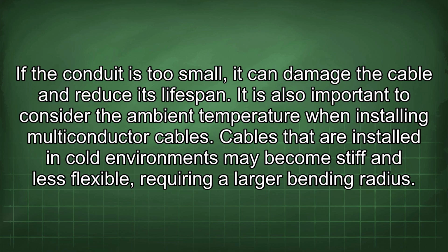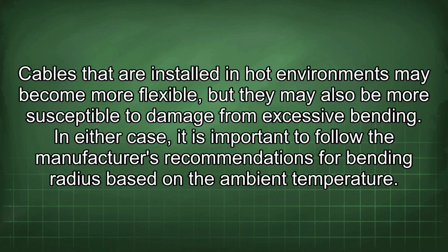It is also important to consider the ambient temperature when installing multiconductor cables. Cables that are installed in cold environments may become stiff and less flexible, requiring a larger bending radius. Cables that are installed in hot environments may become more flexible, but they may also be more susceptible to damage from excessive bending. In either case, it is important to follow the manufacturer's recommendations for bending radius based on the ambient temperature.